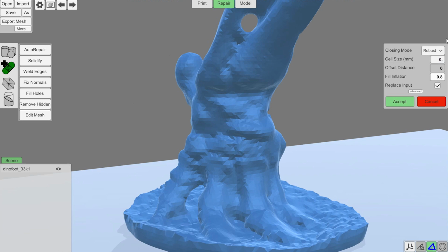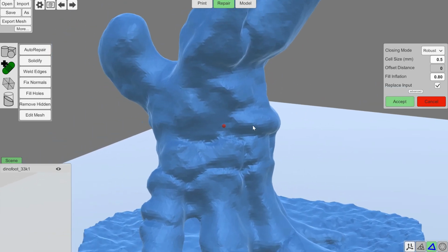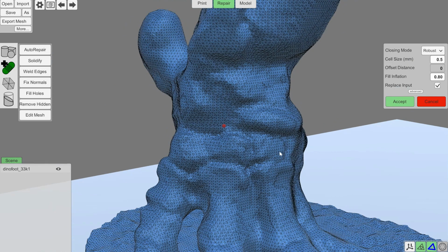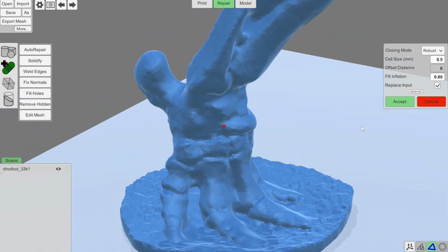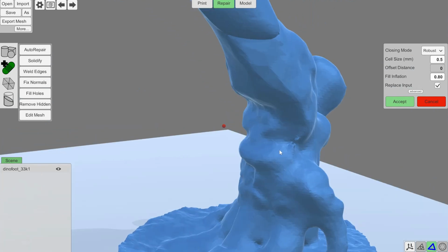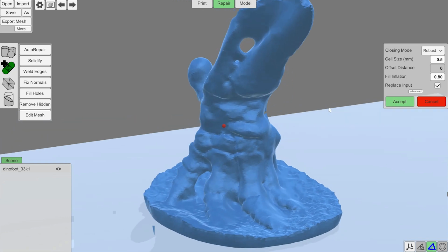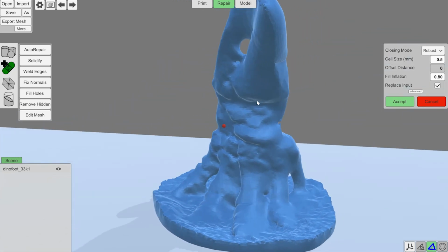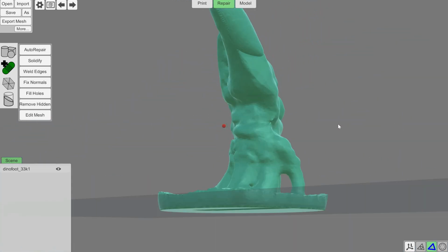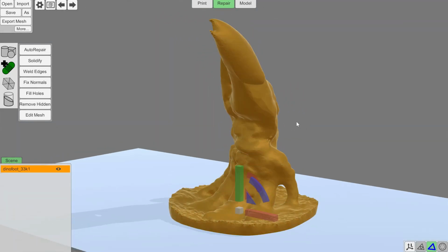As you turn up the cell size, it's going to take longer. So if I change that to 0.5, my computer is going to work away a little bit. You might be able to even hear it. And it does a better job of getting the shape. And you can turn that up. If you were trying to create a production result here, you might turn that up even higher and then remesh it afterwards, or reduce it down to something lower density. But there we go. You see it filled out the bottom even more here. Okay, so there's one example.